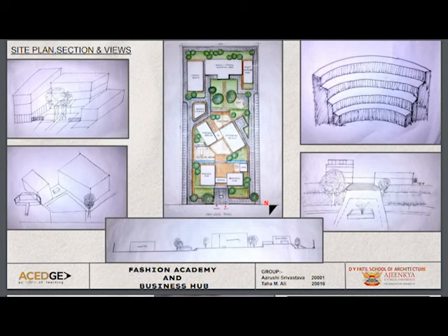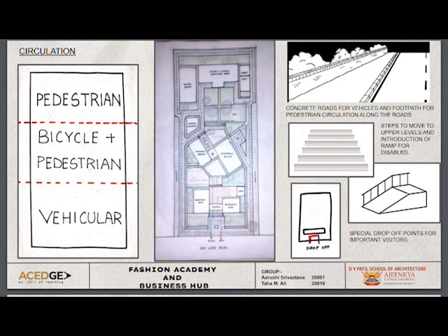These are some views. This is a circulation map of the campus. The campus is divided into vehicular and pedestrian zones. The roads here are 7.5 meters wide and the circulation is two-way. The parking is provided on either side of the campus. The road on the periphery is a service road, which you can see here, and the rest till here is the vehicular zone. The vehicles will be stopped at the hostel gate and will be allowed only in special cases. And the rest is the pedestrian pathway. Different mediums for circulation are used.